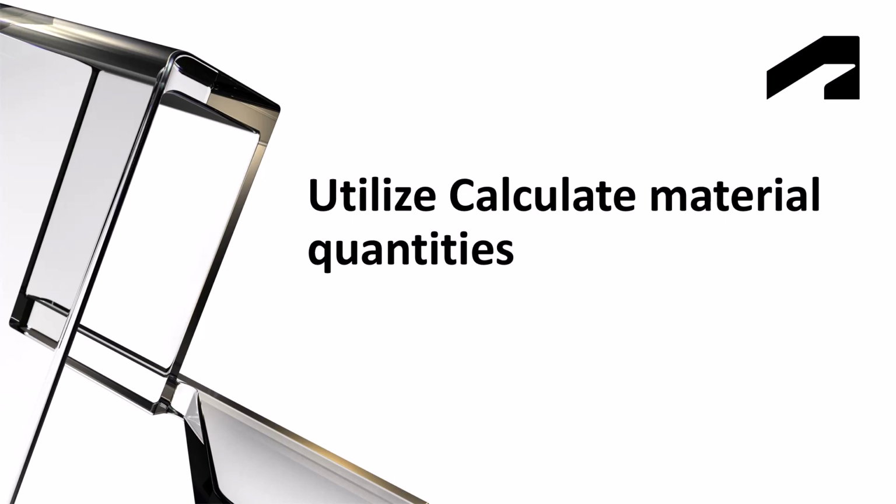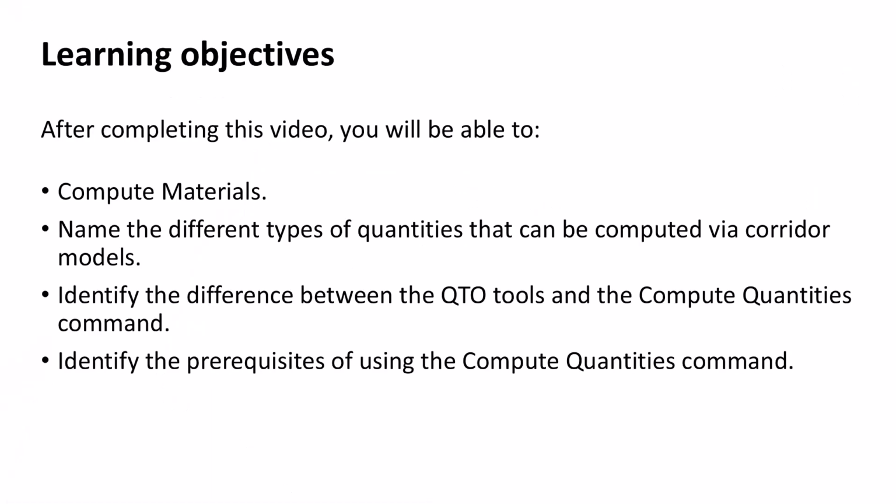Utilize Calculate Material Quantities. After completing this video, you will be able to compute materials, name the different types of quantities that can be computed via corridor models, identify the difference between the QTO tools and the Compute Quantities command, and identify the prerequisites of using the Compute Quantities command.